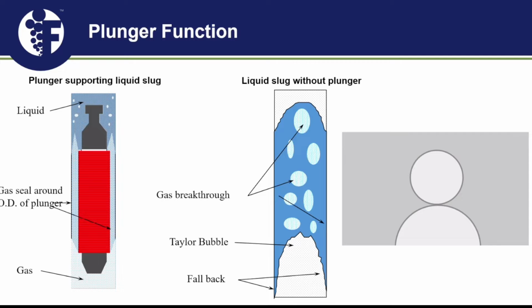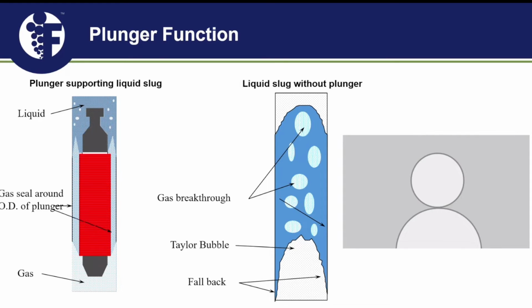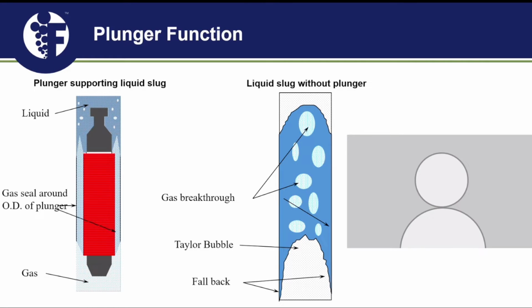And so when we introduce the plunger into that type of well, the plunger essentially minimizes that liquid holdup and fallback. It acts as a seal to hopefully evacuate all those fluids out. And a cycle is what we're going to talk about, but essentially it's just a bite of fluid that it pulls out, right? So that's what we're going to talk about today.